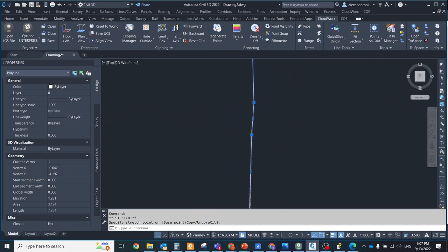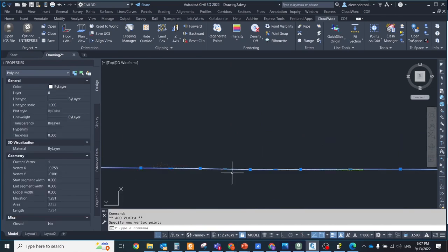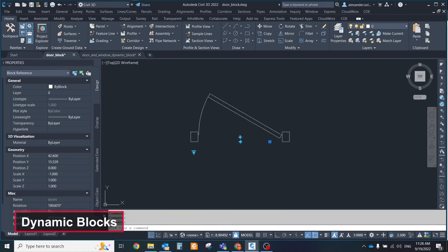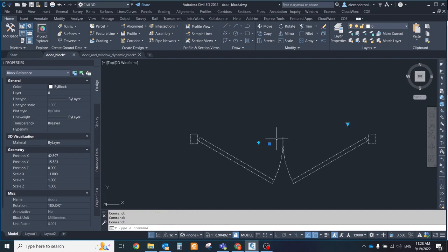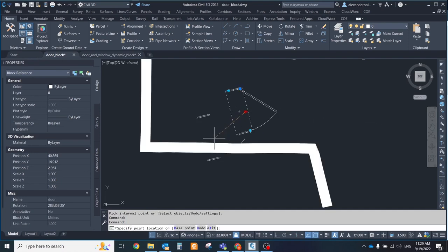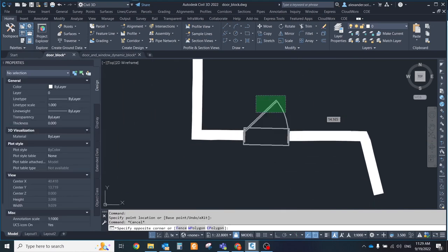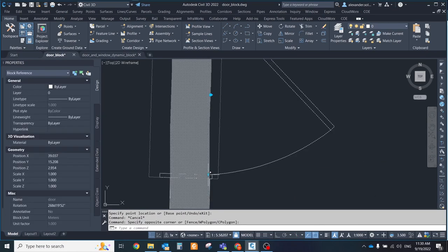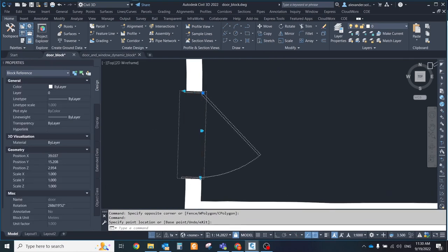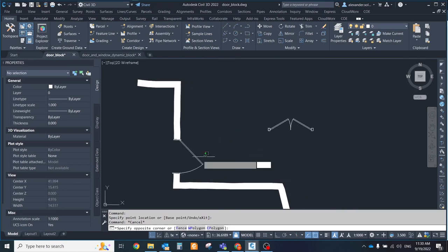If you need to add a vertex manually, hover the mouse cursor over the middle snapping point of the line and press the A button on the keyboard. After all main walls are finished, add doors and windows. I recommend using dynamic blocks for that. They are available in AutoCAD and BricsCAD. Dynamic blocks contain rules and restrictions that control the appearance and behavior of a block when it is inserted into a drawing or when it is later modified. You can add different visibilities, modes for blocks and rules for alignment according to the polyline. Below you could download a small example of the dynamic blocks.